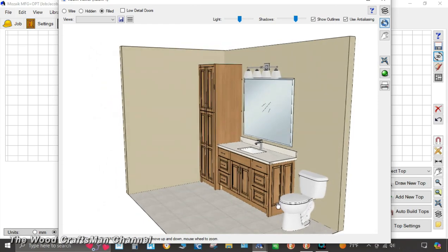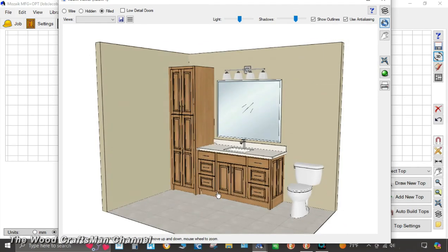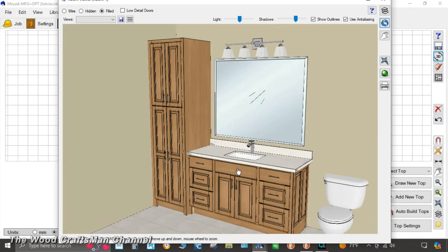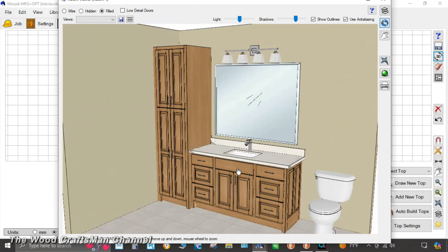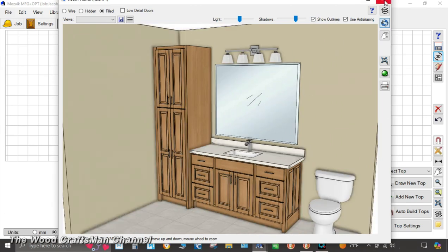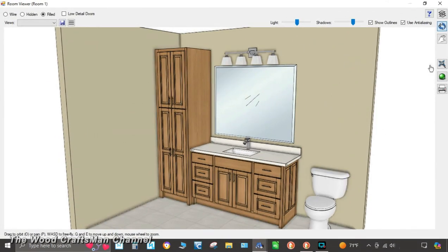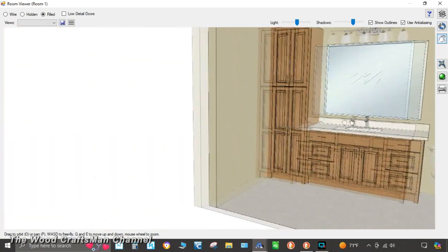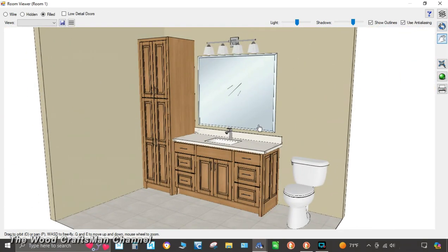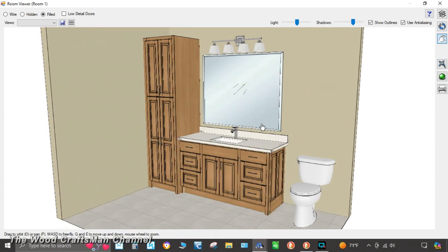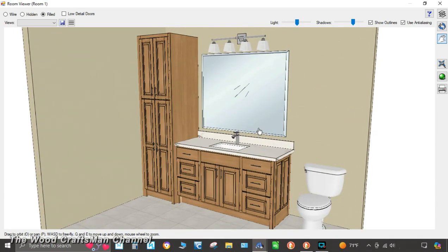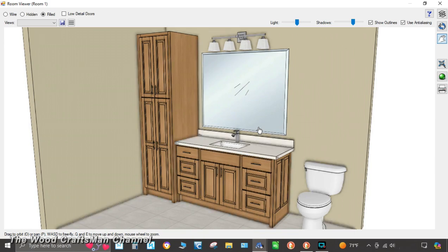Oh, we need to put a door here yet, but this is kind of what we're looking for here. So actually I'm going to do one more thing here as long as we're in here. I'm going to move this around a little bit. So now I've got the orientation right, but I want to raise it. If you click on the hand button, the hand will allow you to move left or right, up or down without changing the orbit. And I will back out one.